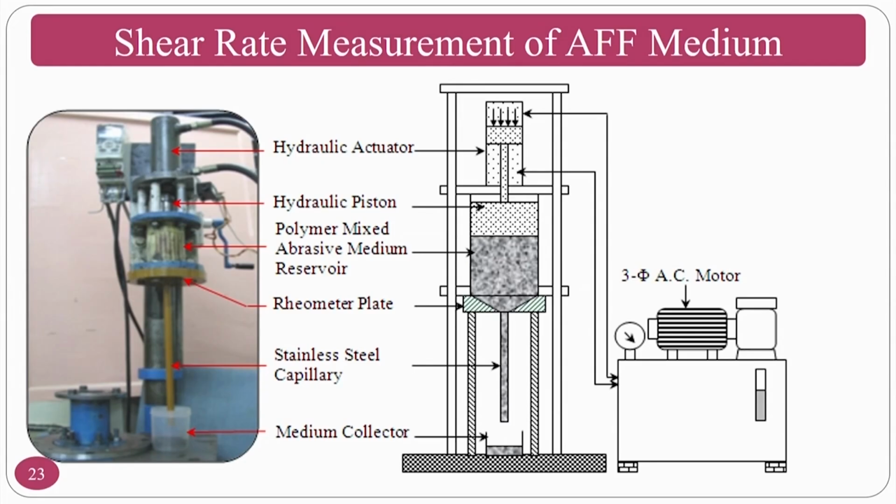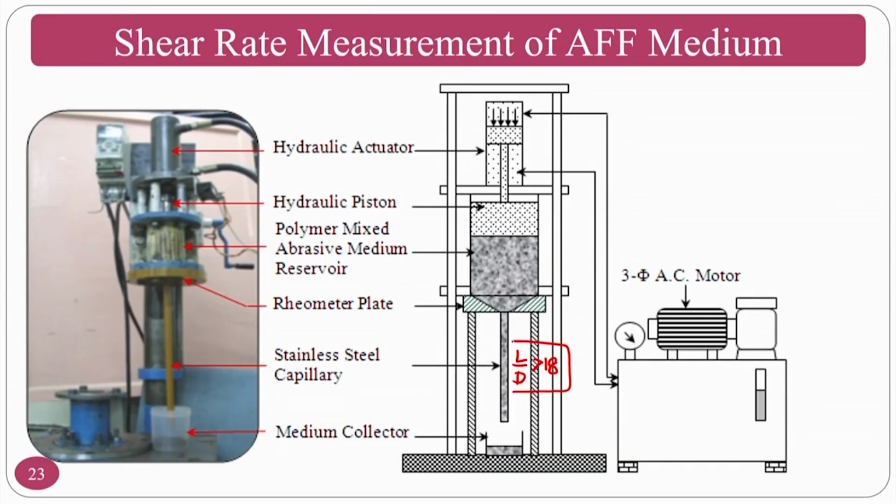For that purpose, one has to go for a capillary rheometer. In this capillary rheometer, normally the L by D of the capillary should be greater than 18.